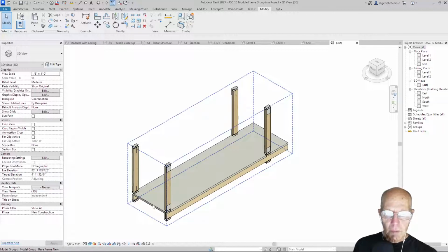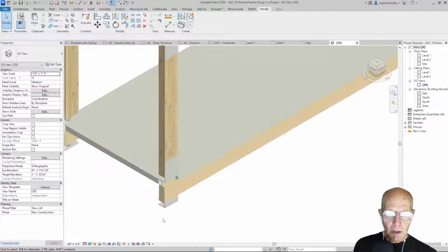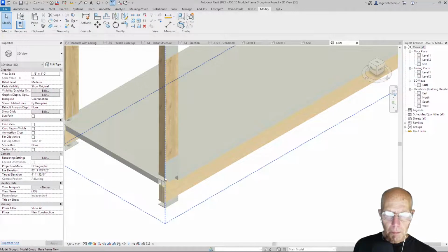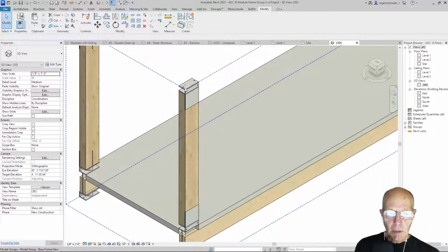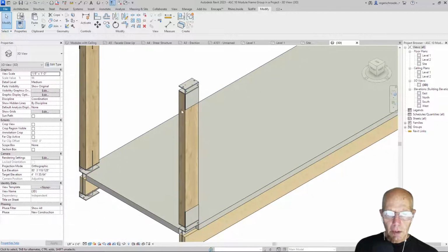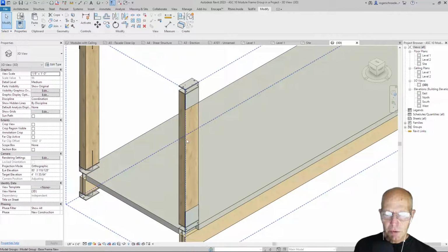So we have a mass timber floor deck. If I zoom in here, we have mass timber beams going across. And then we have this kind of mechanical assembly or connection between the two heavy timber elements. If you think about it, when two of these units go together, each one is creating half of the mass timber system. Otherwise, we would have double. So I've cut the mass timber down in half, at least theoretically, and then I've attached these bolting plates to bolt units together.